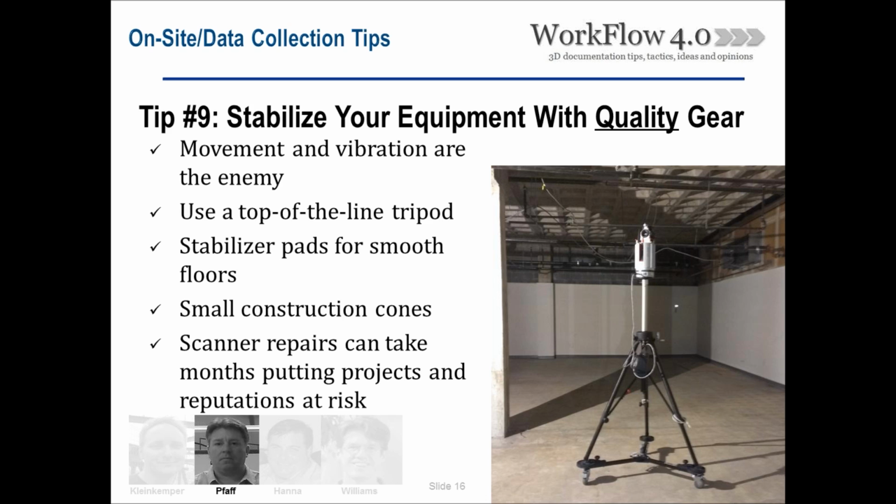Stability of the equipment. We do a fair amount of rooftop work along with our MEP initial. A lot of times we'll be in New York doing high-rise work, and there happens to be a lot of vibration or just areas that you weren't prepared for to go up there with your tripod. You'll end up punching holes in the roof and causing leaks and various other things. So I guess the idea is to get the most stable and safe setup for your $100,000 scanner that you happen to have up there.